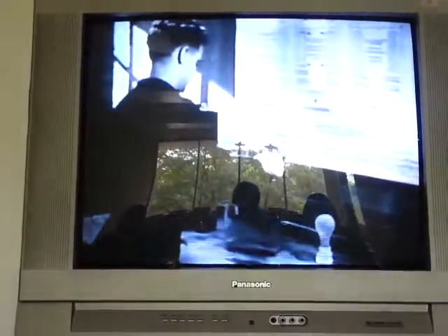This is a secondary cell. It may be renewed by forcing electric current through it in the direction opposite to its discharge. This storage cell has lead plates in a solution of sulfuric acid. A standard storage battery is made up of several such cells connected in series. The EMF of a storage cell is about 2 volts.